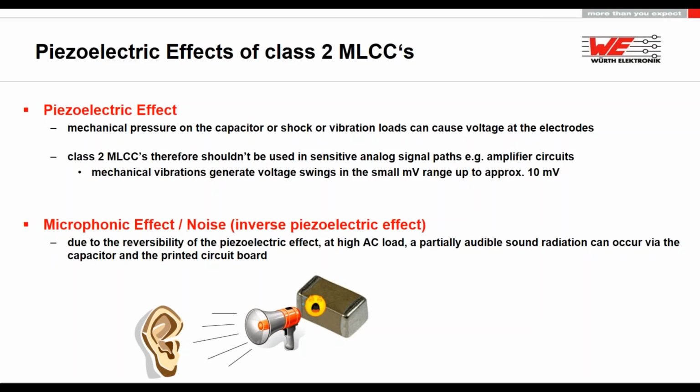And the inverse piezoelectric effect, if you have frequencies in the hearable range on the ceramic body or applied in the application, this can result in the opposite way, that the microstructure will start to vibrate, and this will result in partial audible sound radiation. So this can be pretty noisy as well.